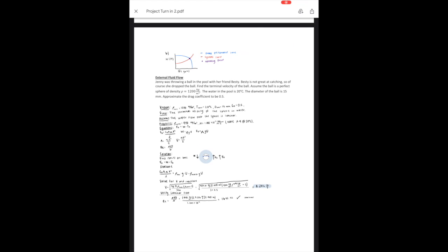We did sigma over D, the roughness, and then f prime again, but this time for laminar. So you can find the head loss of pipe 2 and then the total loss. You just sum those together, and then you find the total required pumping head. For part B, this is just a typical pump curve. You see the pump performance curve, the system curve, and the operating point, and the SI units are feet and gallons per minute. So this next problem covers external fluid flow.